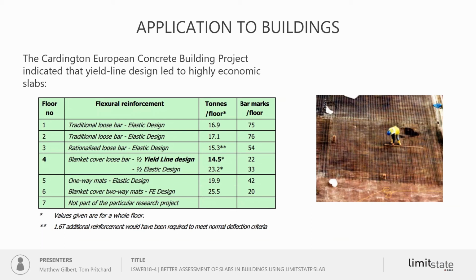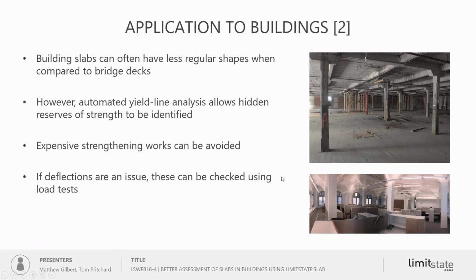They used yield line design methods to design floors in the Cardington European concrete building project, and what they found was that the use of yield line methods led to reduced tonnage of reinforcement and also simple patterns of reinforcement. Compared with elastic design, where you might have lots and lots of bar marks per floor, you end up with much more modest numbers, but also low tonnage.